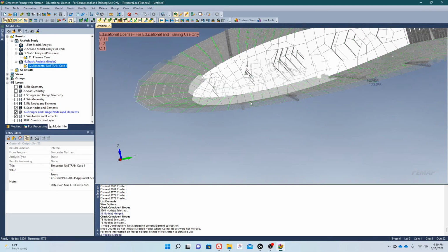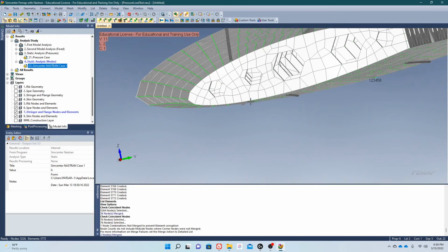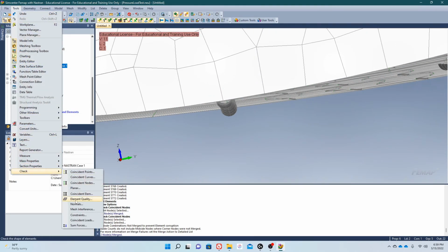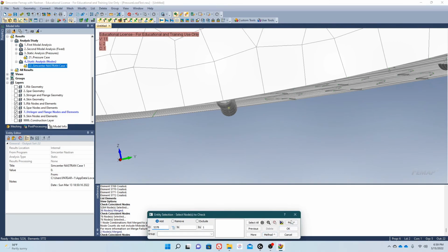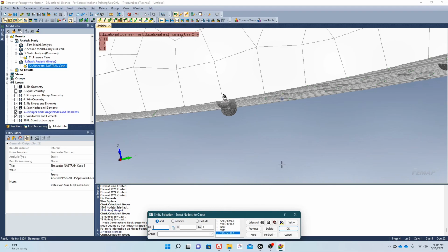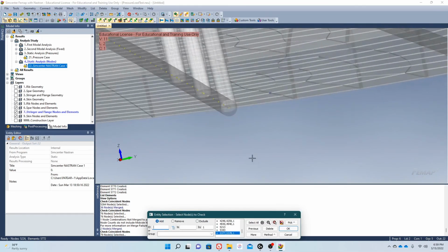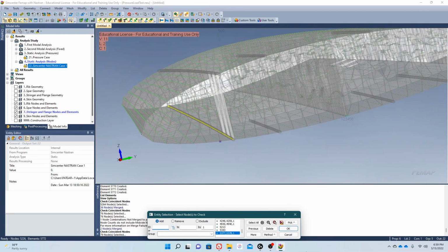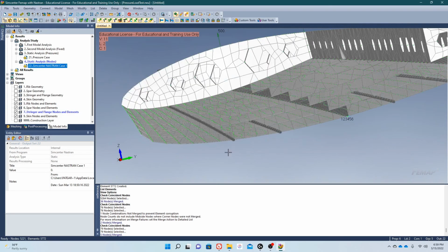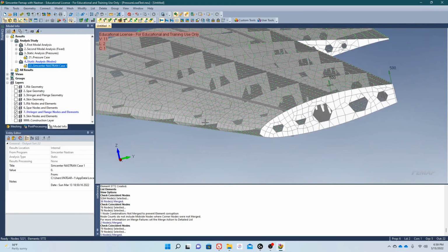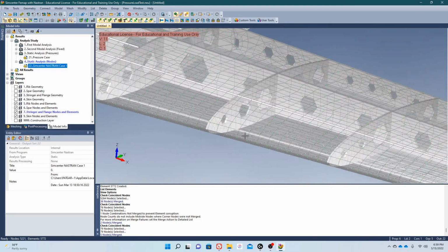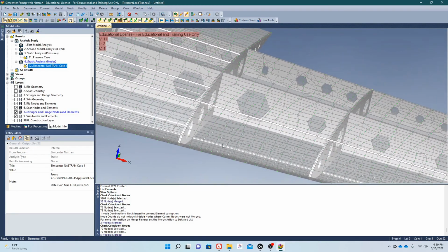And we're going to do the same thing for this one here, bottom stringer. Pick the polygon, all those nodes that it's selected, press OK, and 1/2 inch, 5 nodes merged. Now, let's visually look at the model one last time before running it to make sure that there's not going to be any fatal errors that arise.